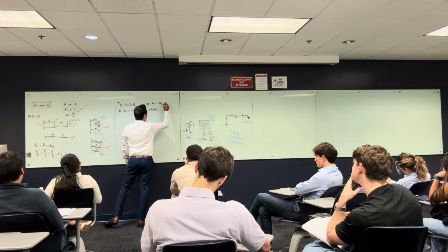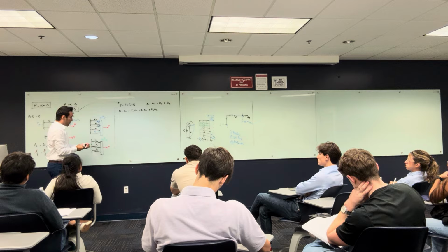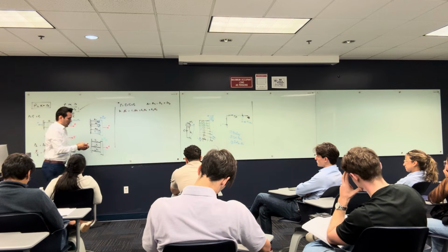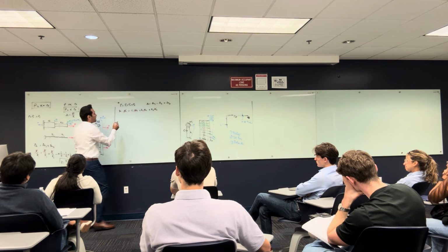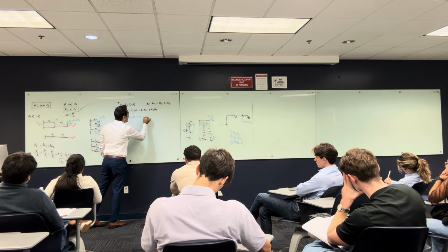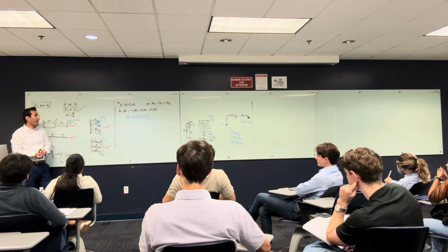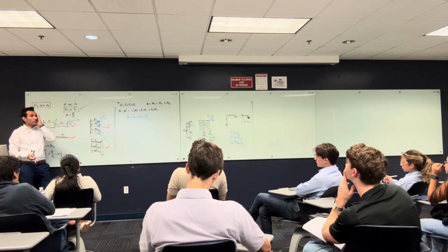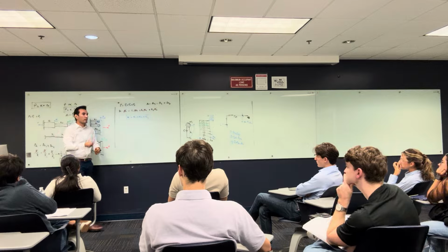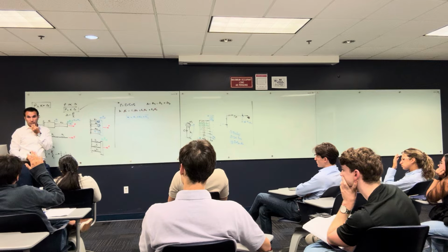Knowing that delta equals delta 1 equals delta 2 equals delta 3, I can divide by delta, so all these are gone. This gives K equals K1 plus K2 plus K3. Did you get that? Did you study electricity, the resistance of a circuit? It's kind of the same thing, like resistances in parallel or batteries in parallel and in series. It's kind of the same concept.